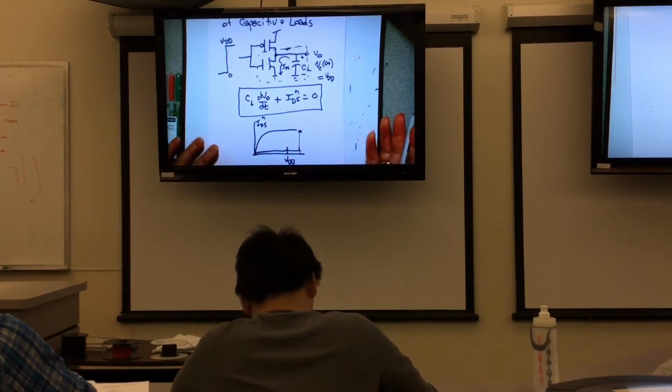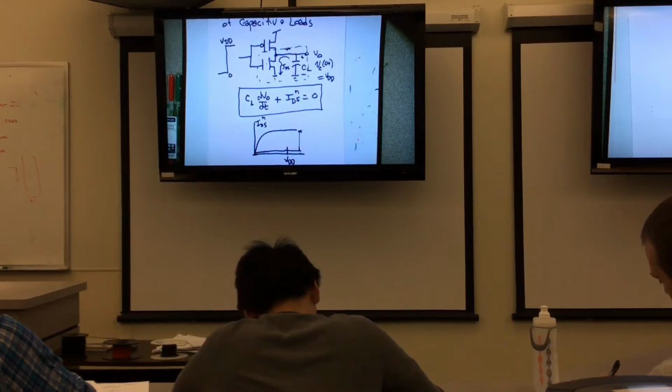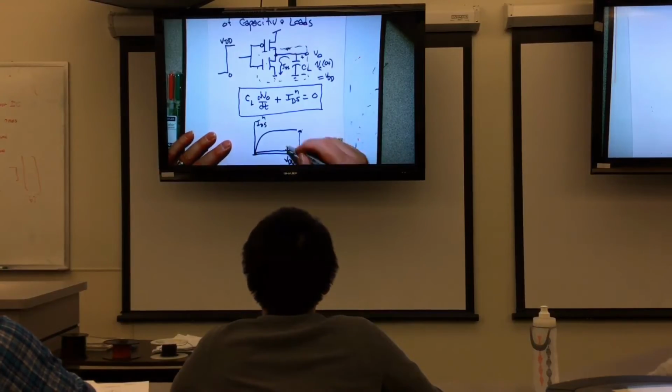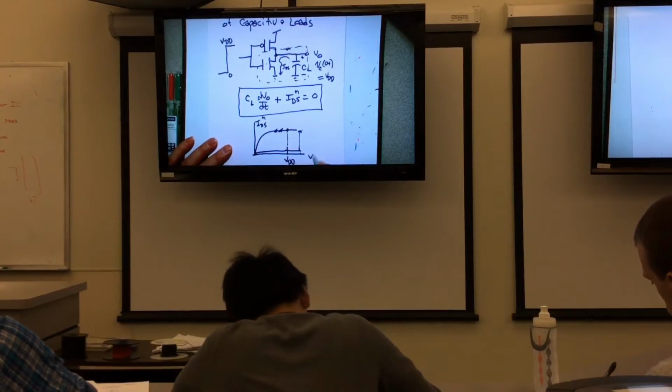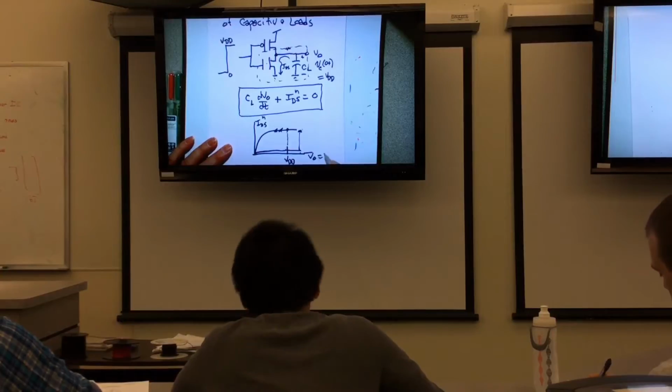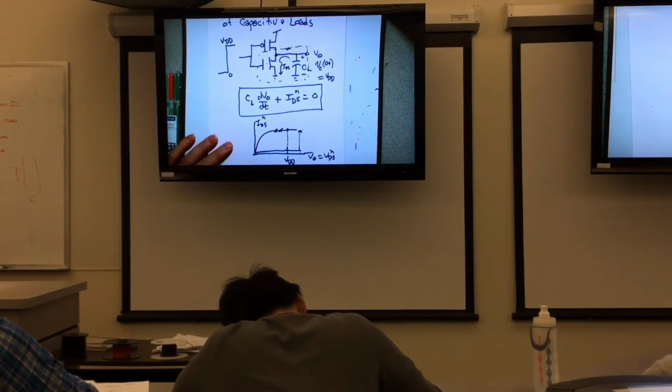And it happens so quickly that essentially the capacitor is like an inertial element that can't change its voltage properly, and so it's sort of stuck at that voltage. Then as soon as the switch is on, you're going to begin to drain current off the capacitor. And the voltage at the output, which is also VDS from the N-type device, is going to decline.